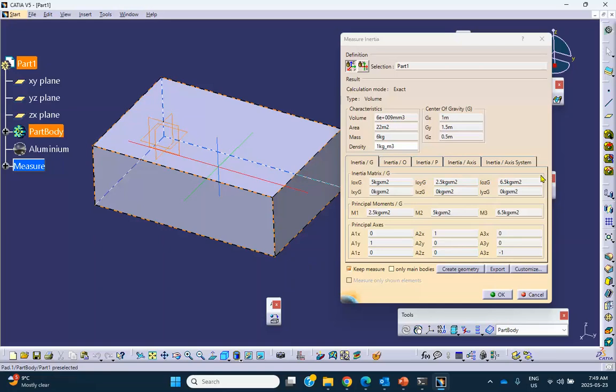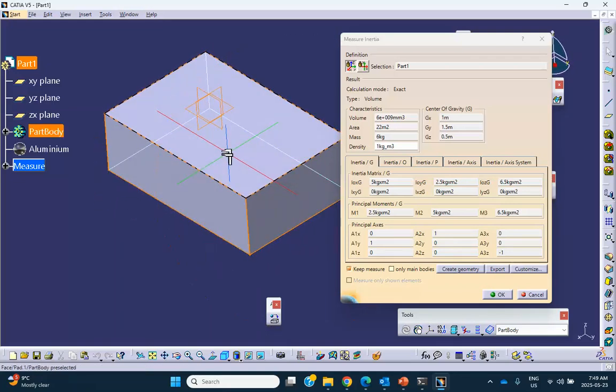So there we are. And it's not surprising that the products of inertia are zero, because when the selected point is your mass center in this particular problem, the products xy, xz, and yz are zero when the coordinate system is placed at this point with planes of symmetry.